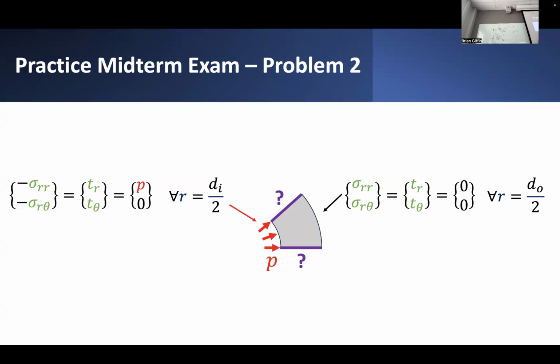So if we said the solution on either side of that symmetry plane should look the same, does it make sense to have a circumferential component of displacement, such that along this half of the body this point wanted to displace in the circumferential direction, but on the opposite side the displacement did the same thing in a reflected fashion? It would look like across the symmetry plane, you're violating conditions of compatibility.